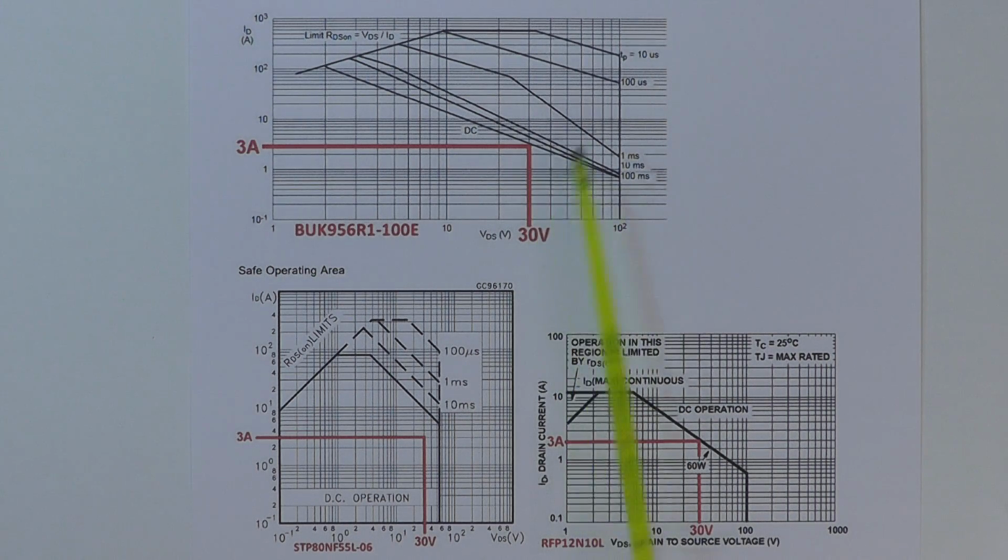You'll see on the information sheet I'm going to give you as a download, there is a power derating factor above 25 degrees, which indicates how many watts or fraction of a watt it will reduce for every degree above 25 degrees centigrade.